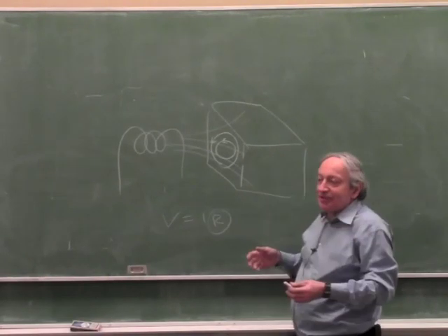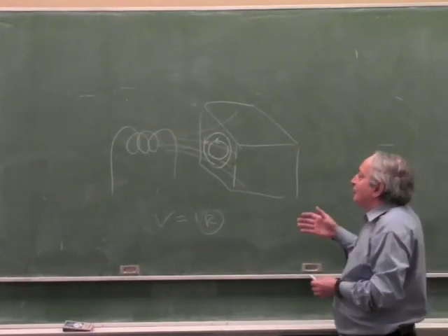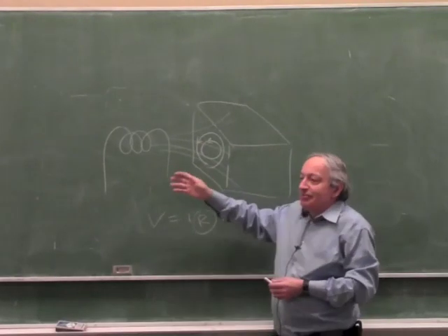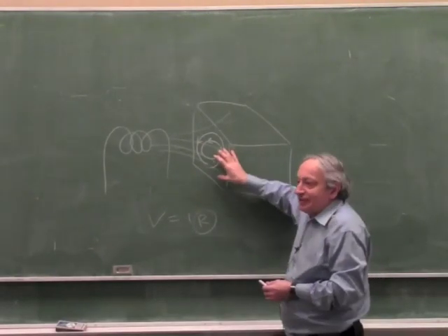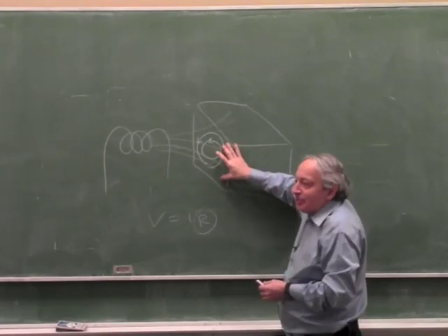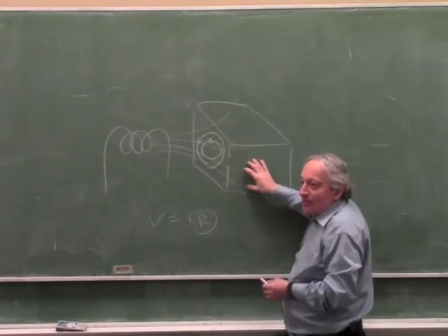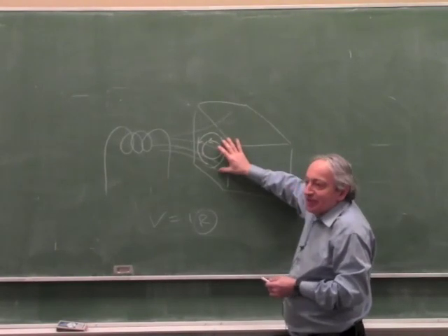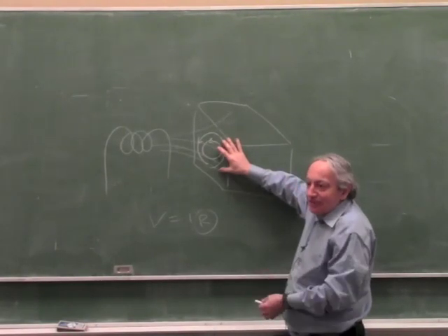But with practical materials, steel is good against the magnetic field, but then the steel has high resistivity, so it actually allows quite a big potential difference. If you take copper, it is a good conductor. It doesn't allow high potential difference, but it doesn't stop slow magnetic fields.